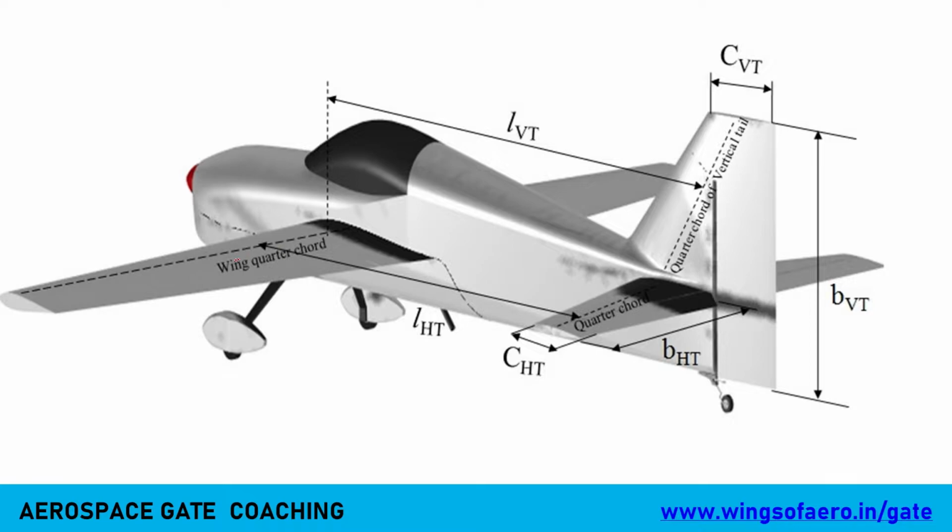For the distance between the quarter chord of the wing to the quarter chord of the horizontal tail or stabilizer, similarly, this is the tail lever arm. This is a very important parameter to decide the stability factor.